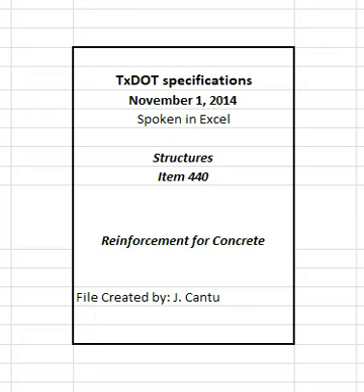Patch no more than 1/4 inches total length in any foot at the applicator's plant. Maintain identification of all reinforcing steel throughout the coating and fabrication process and until delivery to the project site. Furnish 1 copy of a written certification verifying the coated reinforcing steel meets the requirements of this item and 1 copy of the manufacturer's control tests.